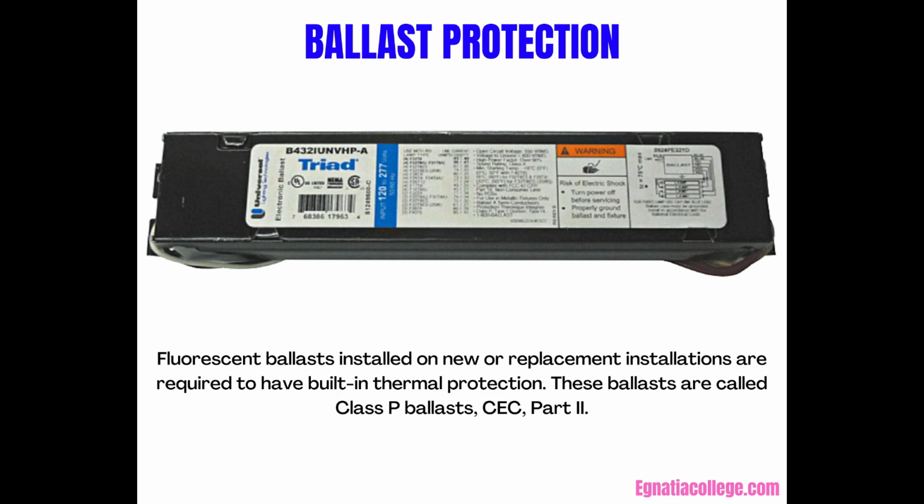Some Class P ballasts also have a non-resetting fuse integral with the capacitor to protect against capacitor leakage and violent rupture. The Class P ballast's internal thermal protector will disconnect the ballast from the circuit in the event of a high temperature. Excessive temperatures can be caused by abnormal voltage and improper installation, such as being covered with insulation. The reason for thermal protection is to reduce the fire hazard from an overheated ballast. Ballasts can overheat if they are shorted, grounded, covered with insulation, or lack air circulation.